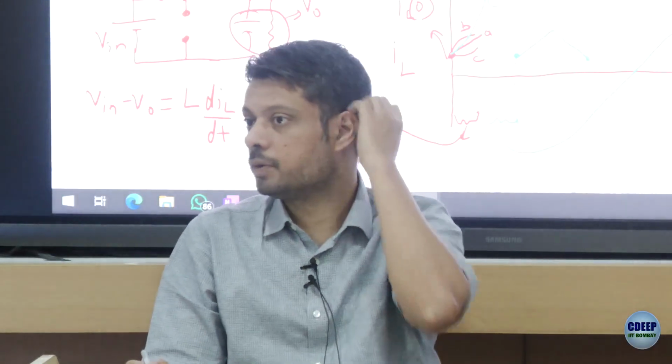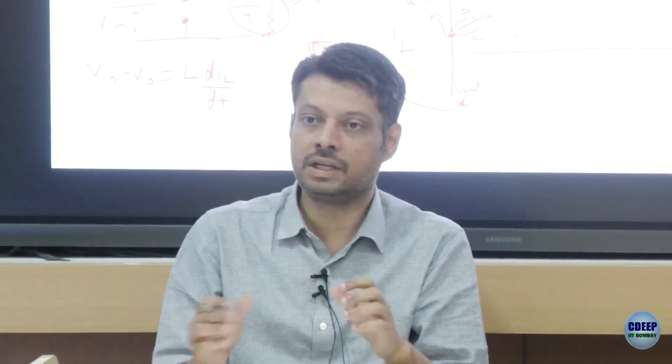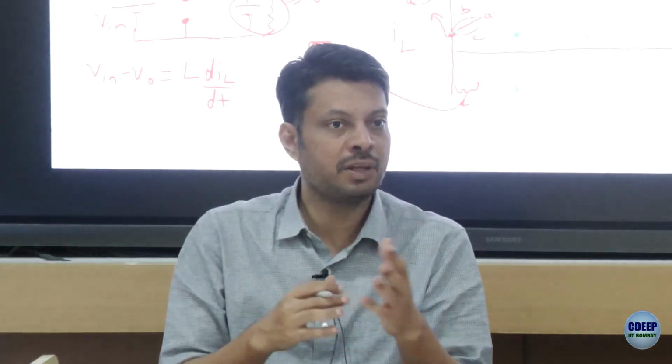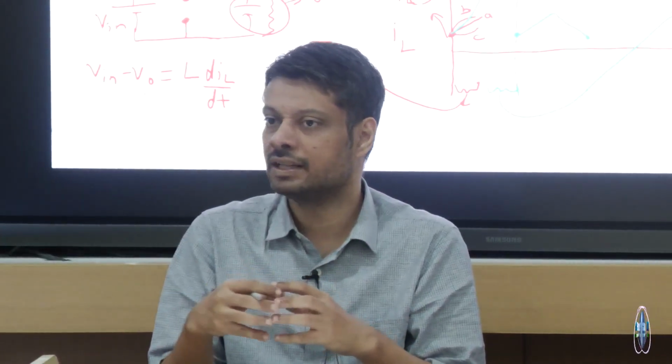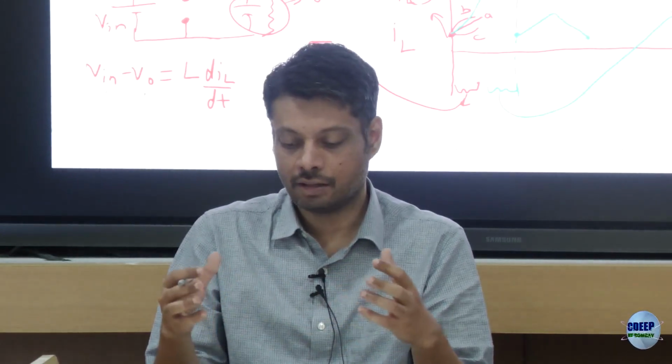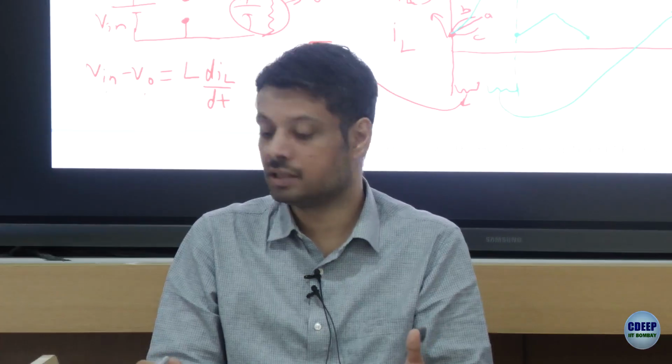So last time we were talking about the DC to DC buck converter, right? And we saw that a buck converter is, in a way, a combination of some switches which convert DC voltage into high frequency alternating voltage, and then there is a filter which removes the high frequency component and only keeps the average or the DC component, and thereby you get an output voltage which is a variable voltage which you can control using the duty cycle.